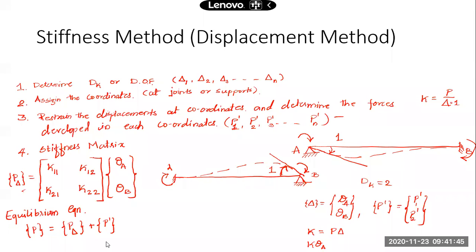I want you to tell me any doubts if you have when you are developing the stiffness matrix. What I considered was a case of 2 degrees of freedom. If there are 3 degrees of freedom, you'll have a 3 by 3 stiffness matrix. You'll take the first coordinate and give unit displacement in the first coordinate without giving displacement in any other coordinate. Remember that. When I'm working with the first coordinate, I'll give unit displacement only in the first coordinate, and not in the other coordinates.